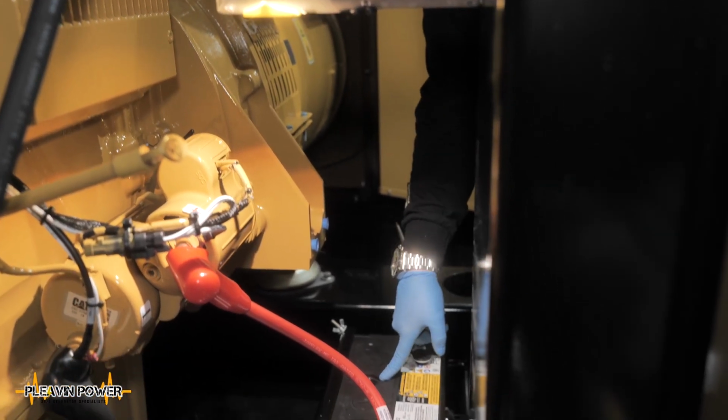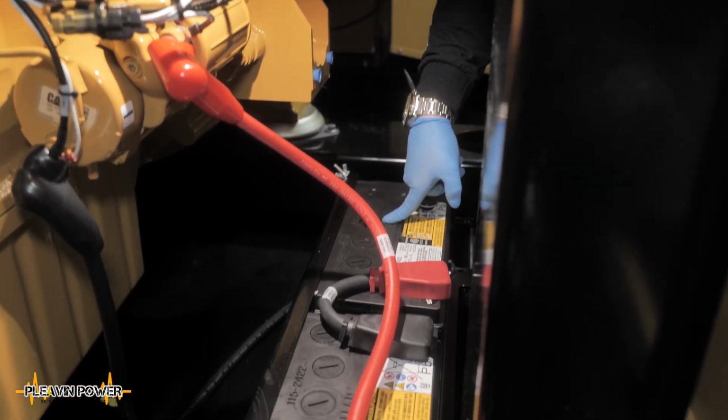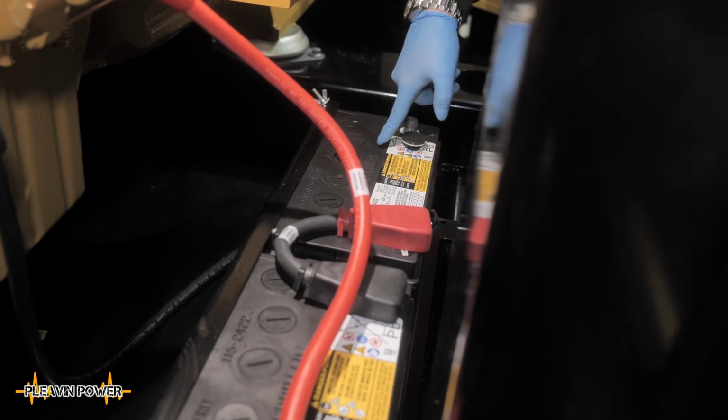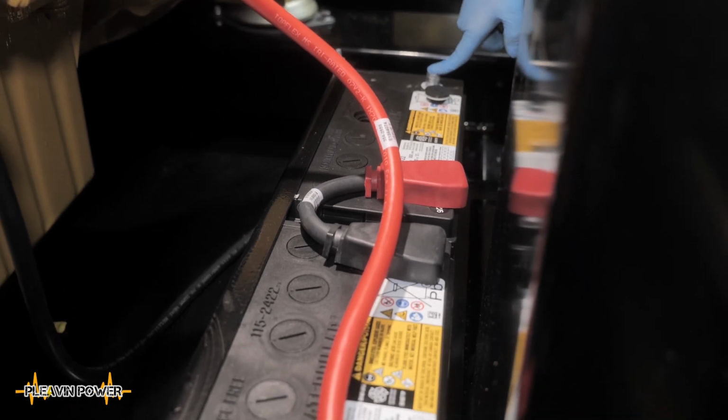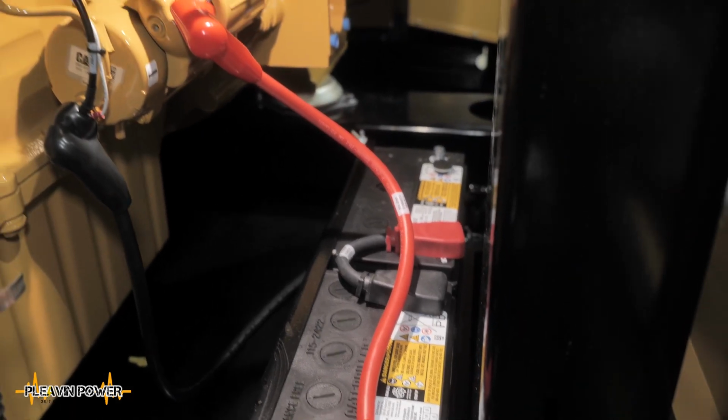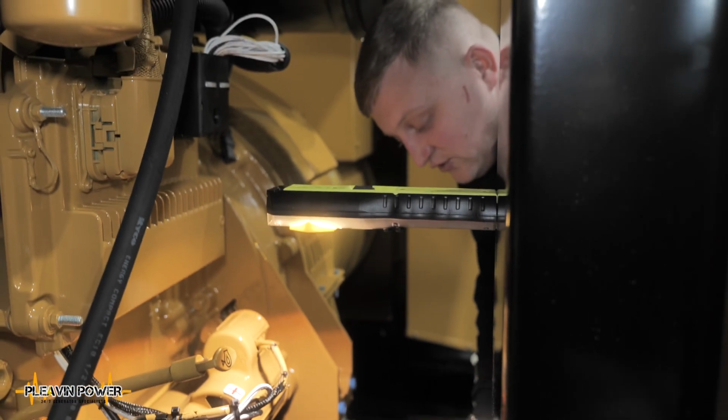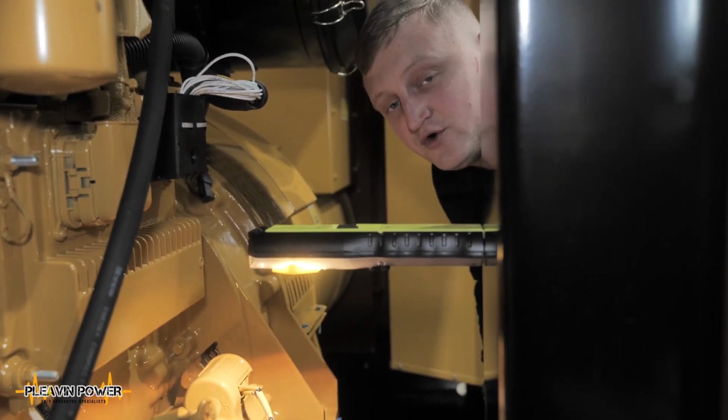Failure to do so will cause premature battery failure or premature deterioration, but this can be monitored during the service visit as well by carrying out what's called a drop test, whereby the cold crank amp capacity of the battery is monitored and measured over the time that the service and maintenance visits are carried out, to ensure that if you've got a depleted cell or a depleting battery, it can be replaced before it causes you a failure or a headache.